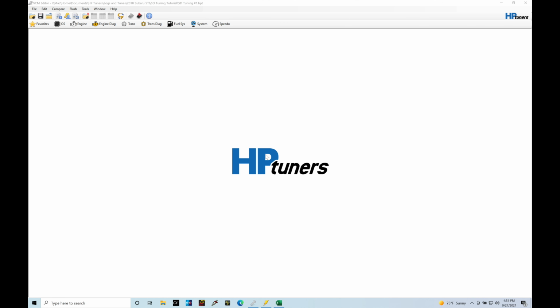Okay, so let's get started. We're going to be taking a look at working with our speed density volumetric efficiency calibration process in this tutorial. We're specifically going to be taking a look at idle, part throttle, and the transition into boost. We're going to be using our VCM scanner to create a custom histogram so we can log specific data, overlay it in our histogram, and repopulate our main volumetric efficiency table. This is going to be a relatively straightforward process, but there's a lot of details we need to get out of the way first to make sure that we're going to be doing this properly.